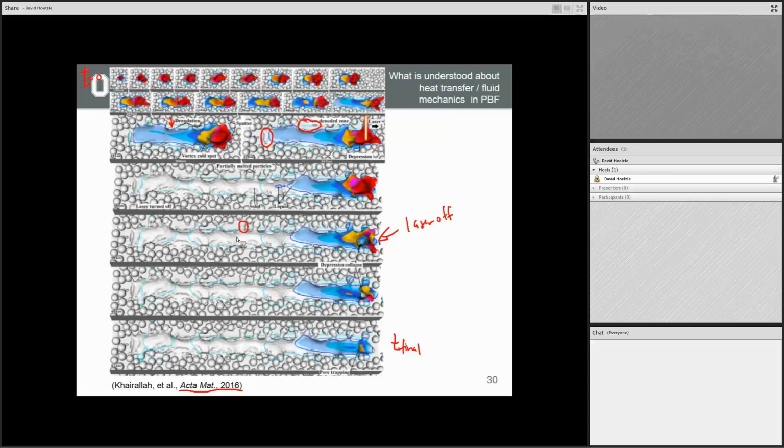Curious, do you think PBF will go the way of FDM printers when the patent expires, just because of all the support structure? Go the way in terms of become less expensive, you mean? People like having their desktop 3D printers. There's a lot more going on here in terms of things that spike the price. In FDM there's basically 4 motors, a heating element, and some computer control. And this has a lot. Anytime you have a system that has regulated air quality, including vacuum pumps, argon sources, things of that nature, it gets much more expensive.